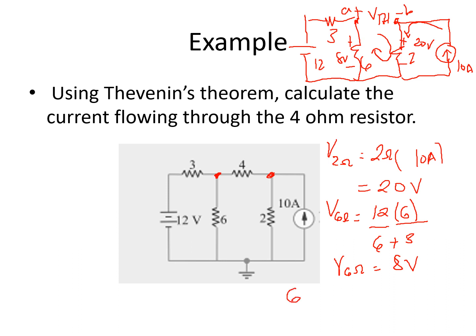We have here minus VTH, we have here minus 20 is equal to 0. Solving for VTH, this is 6 minus 20. That will give you negative 12. Again, what do we mean by the negative sign here? That means that your B here is positive with respect to point A. So we have a wrong assumption.